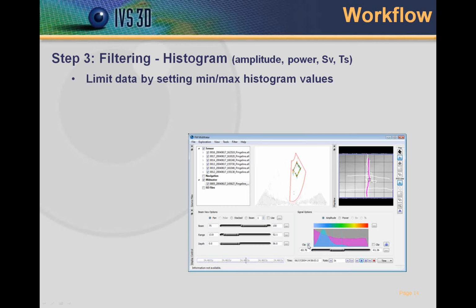And what you can do is either clip or clamp the data. In this case this is the minimum range and here's the maximum range. If I clip the data, everything below this level will be eliminated, and the upper level I'm clamping, so I want to keep my high-level signal noise. It's just that the color map is going to be stretched across this range here. So now I've reduced what's interesting to just this bit here, and now I'm ready for export.